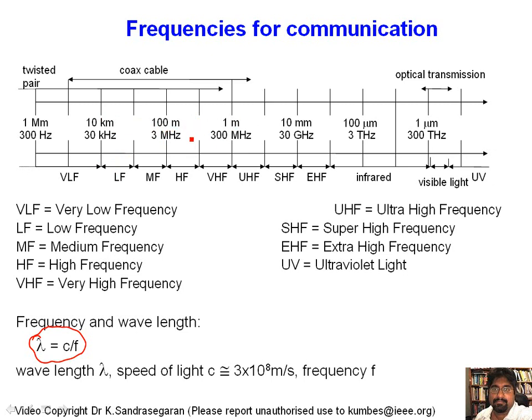One of the things that happens is that the lower frequency bands are getting more and more congested, and as they get more congested, there is no more space available in the lower frequency bands, and consequently we have been pushed into high frequency bands. And as time goes on, we'll find maybe even the UHF band is almost congested. Now we are moving into the SHF band, and from the SHF band we'll eventually have to move to the EHF bands.